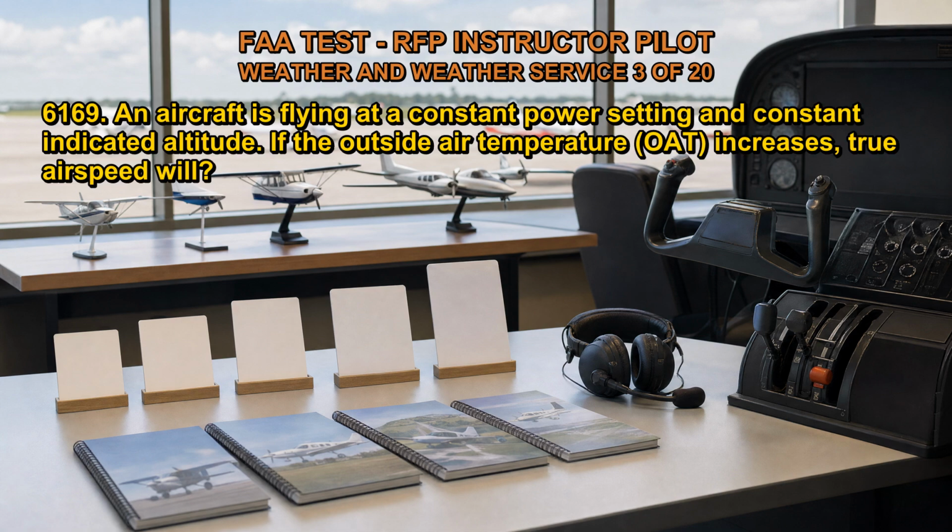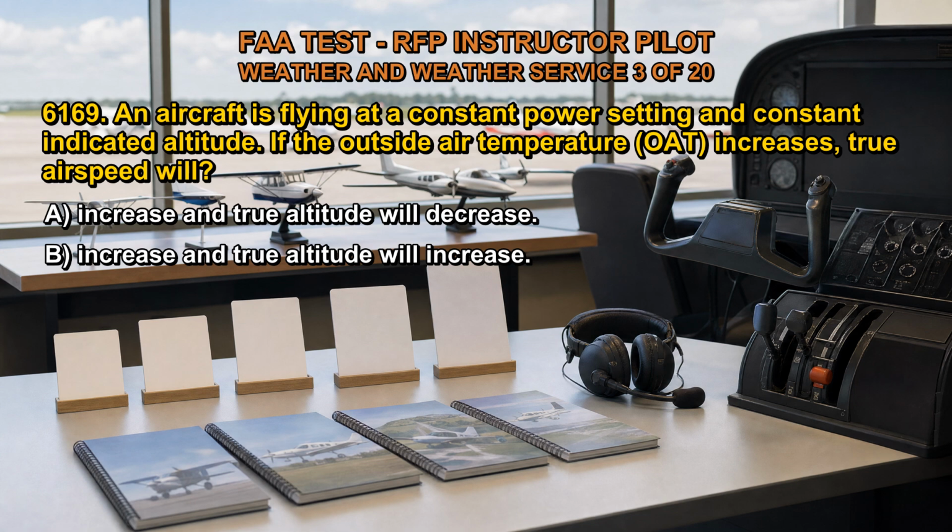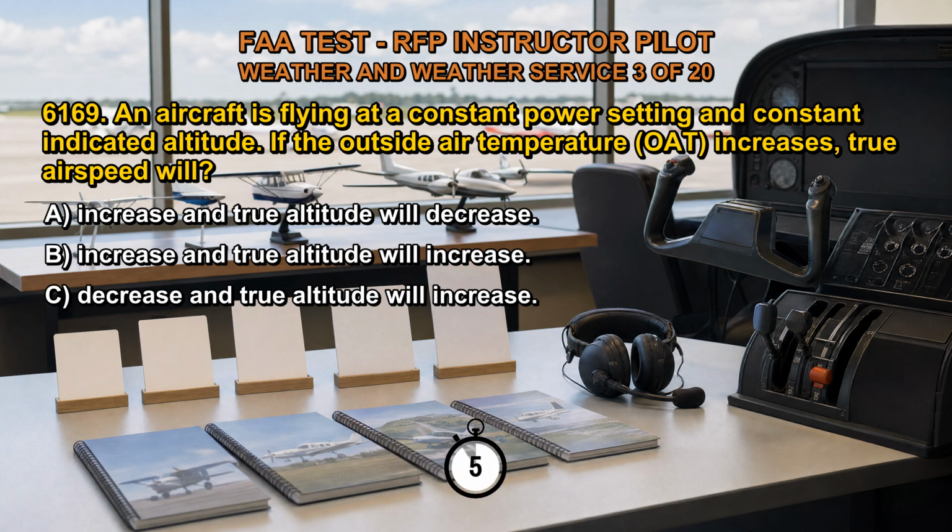6169. An aircraft is flying at a constant power setting and constant indicated altitude. If the outside air temperature, OAT, increases, true airspeed will A. Increase and true altitude will decrease. B. Increase and true altitude will increase. C. Decrease and true altitude will increase. The correct answer is B.